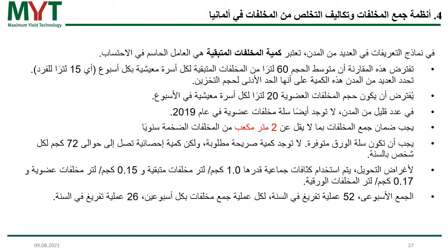But these are the findings which we came up with in Germany. So in the tariff models of many cities, the amount of residual waste is a decisive factor for the calculation. So you don't look towards the bio waste or the paper, you look towards the residual waste. And the comparison assumes an average volume of 60 liters of residual waste per household and week. So we estimate in Germany that one person generates about 15 liters of waste per week. So the model household needs a 60-liter bin per week.